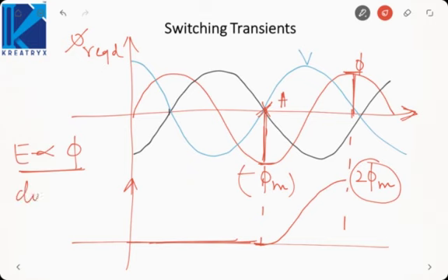This is called the doubling effect. So the induced EMF is also doubled in a short period of time. This is called impulse EMF because high voltage is being generated in a short duration of time. An impulse is a signal which has almost zero duration. So short duration signals can be called impulses. Similarly here, the EMF induced is very high and it has a very short duration. So it can be called impulse EMF.